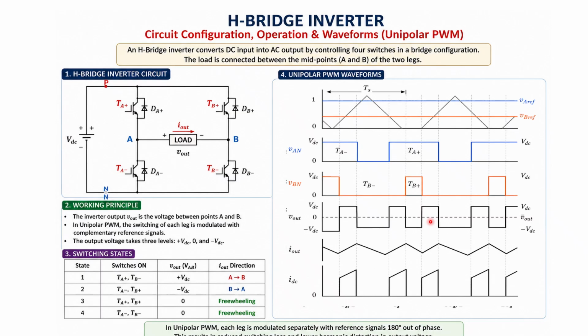So the voltage step transition is VDC, not 2 VDC. Another advantage is that the dominant switching component in the line voltage appears at approximately twice the carrier frequency. Even though both methods use the same switching frequency, the output behaves as though it is switched at a higher effective frequency. This results in a smoother current.